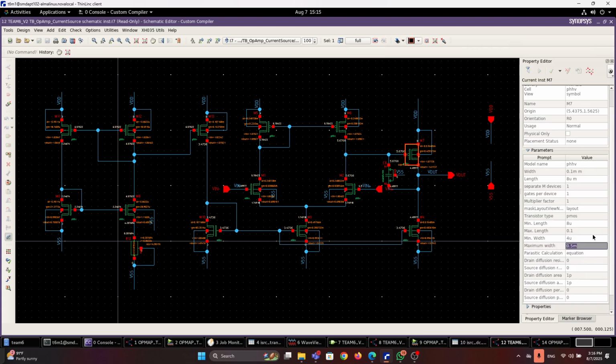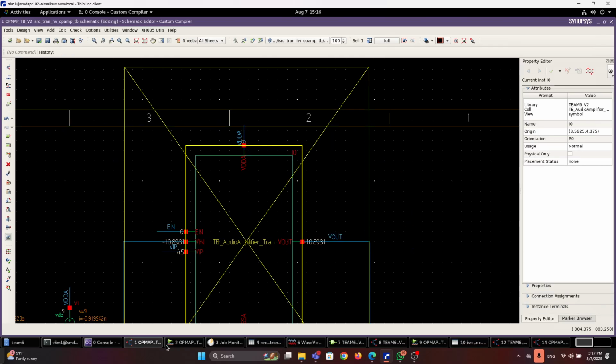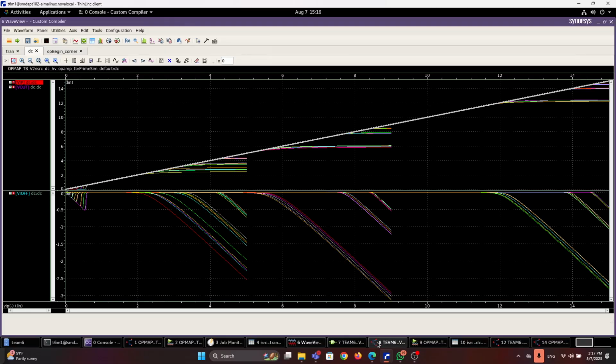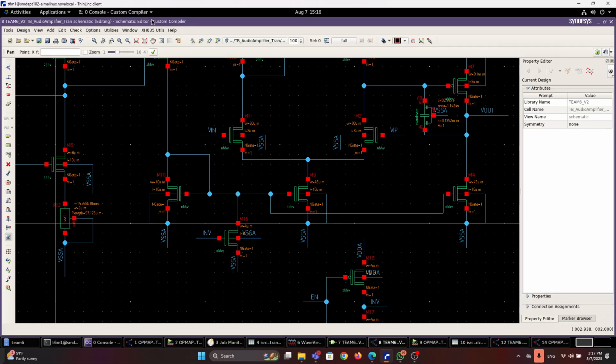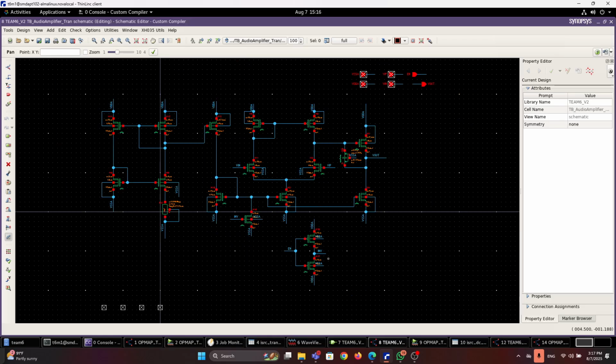Okay. So any other questions? Yeah, go back and work on it first. Remember to put in the enable. In this original one, I don't think you put in. I think the previous V2 version, you got put in the enable and test it out. Maybe start without the enable first, and once you get the op-amp to work without enable, then afterwards you put in the enable.